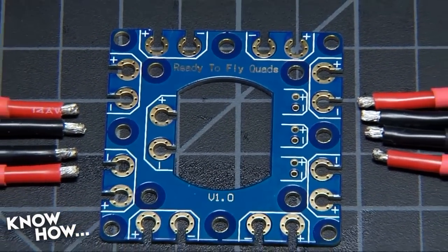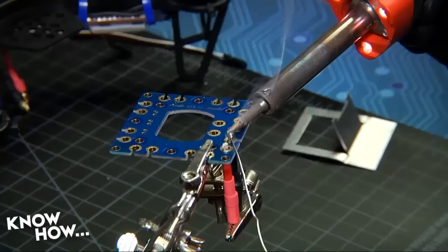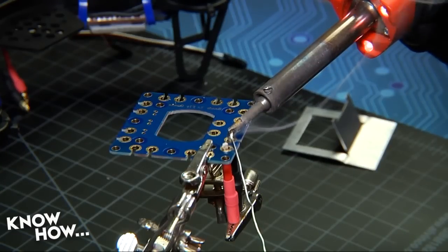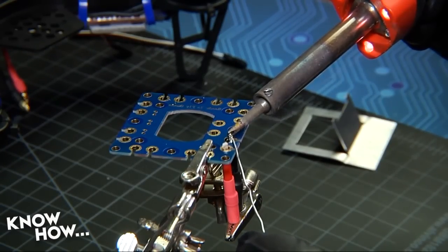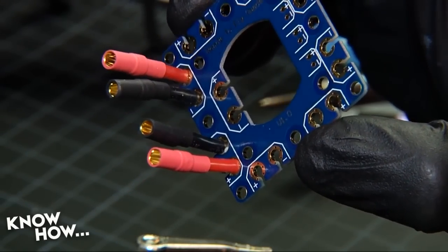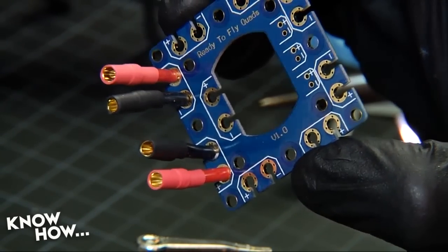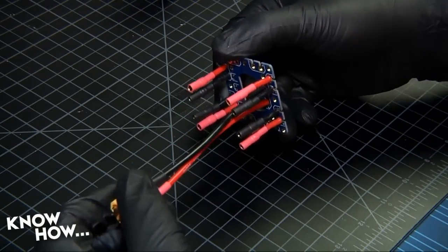Now let's assemble the board. Matching red wires to the positive mounts and black wires to the negative, solder the 1-inch leads to the sides of the boards. Then solder the 5-inch leads to the inside contacts. Mount all your wires on the same side of the board. Avoid an excess of solder, but flow enough to make sure that all the joints are solid. Take special care not to bridge any of the contact points with loose solder.